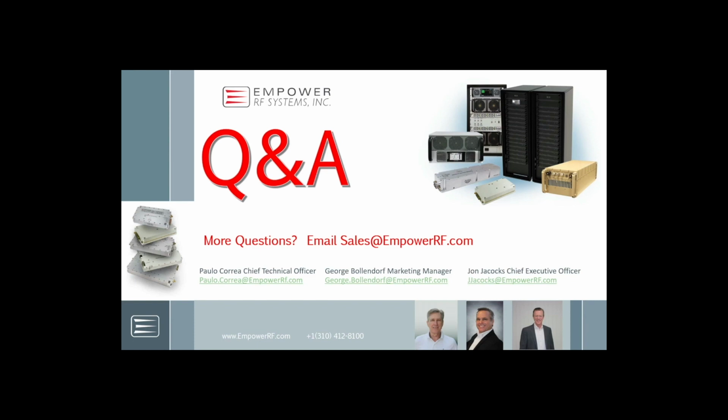Are there cases where you can trade bandwidth for more peak power? Yes, that's true. For example, if you're operating in the infrastructure cell phone frequencies, you're not going to use broadband because your efficiency is going to be so low, and you multiply that by the number of cells, and your cost of energy is going to be very high. So it's very good to use narrowband amplifiers in this case to improve the power consumption.